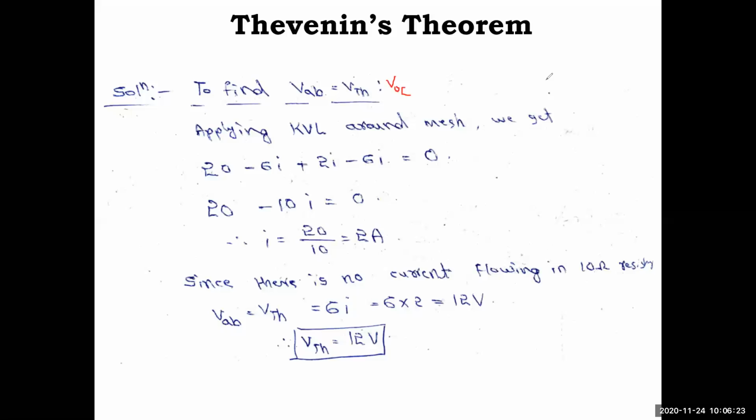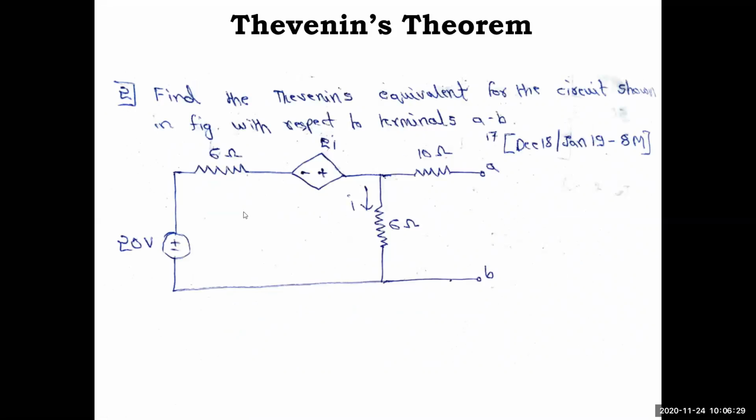So how did you get this? You should not have a problem with KVL and KCL after coming so far. So you have minus plus. When I told you there are two conventions we follow, minus plus we consider as plus 20, and we have taken this direction as current. So current always enters the positive terminal in the resistor case, because it is an absorbing element.